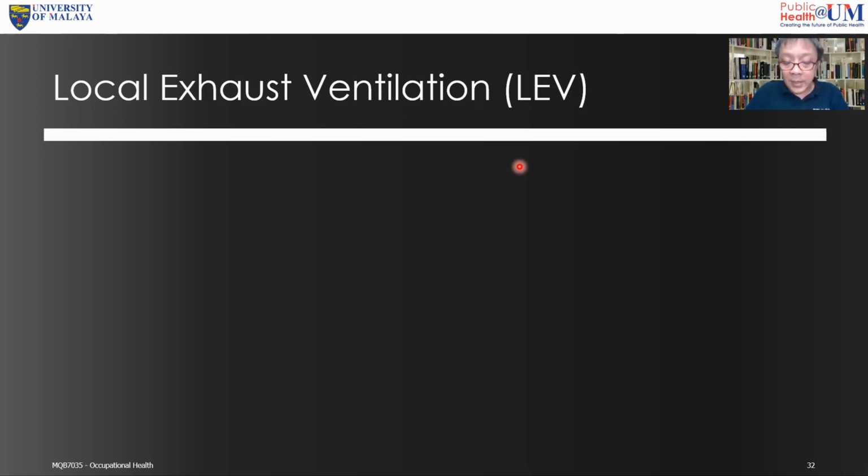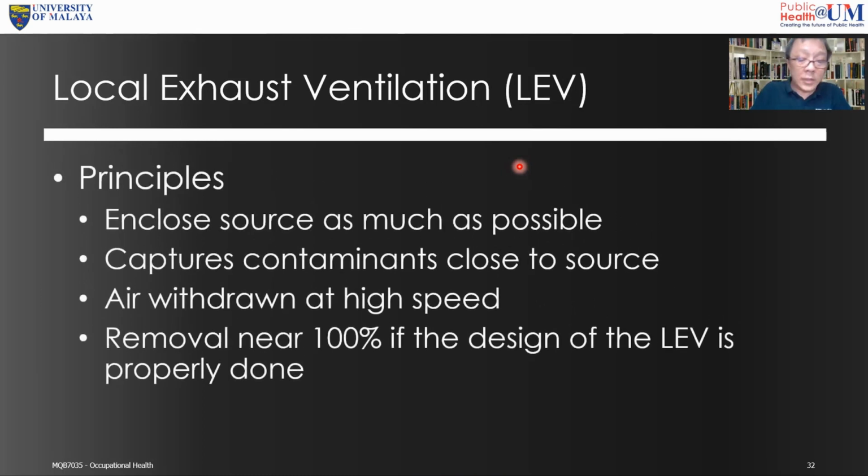That's why it's important to understand that when you are in a laboratory setting, a split air conditioning unit is no, all right, unless your chemicals are only used within a biological cabinet or under local exhaust ventilation. So you cannot use the split air conditioning. So what is the use of split air conditioning? A split air conditioning unit is actually just to cool the air to make the environment more comfortable.